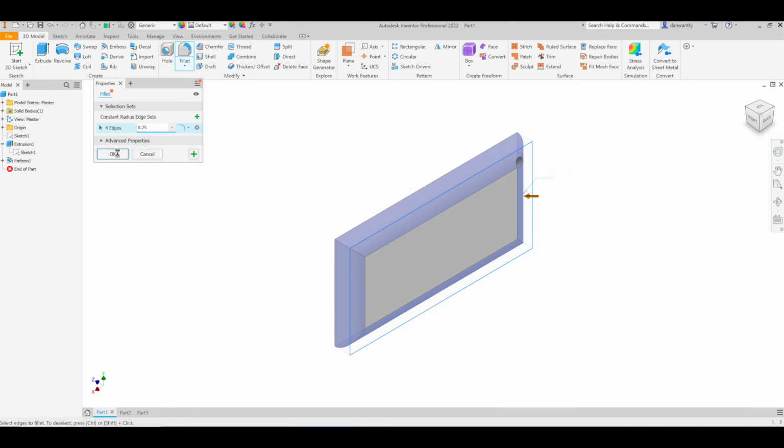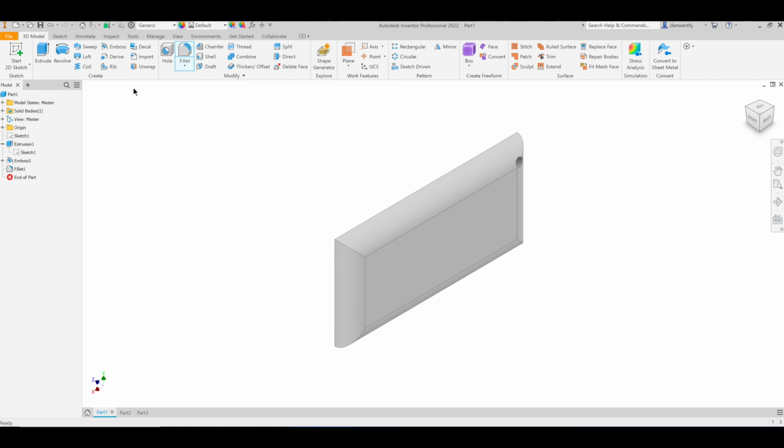We're going to make 2 more fillets, and we're going to do it in a certain order. So the next one will have, as you can see, there are these edges, the ones that are being highlighted in red as I hover over them. These are the edges that you can see that are still sharp. So we're going to fillet those to make them smooth. Alright, let's go over to the fillet tool again.